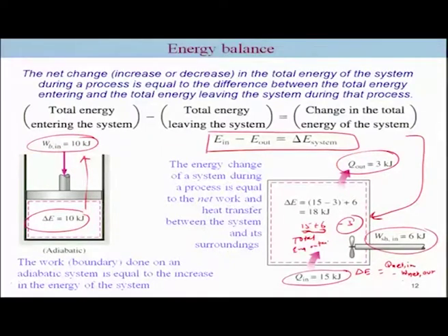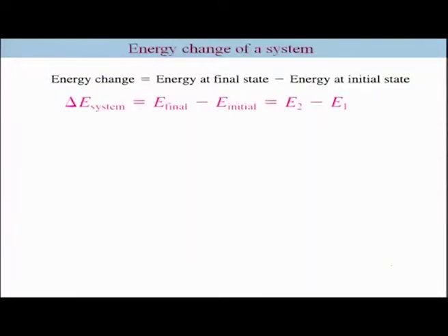Okay. So, what is the Q net in? It is nothing but 15 minus 3. What is the W net out? It is minus 6, and the minus of minus 6 is nothing but plus 6. Thus you can use this sign convention as well as the basic definition without considering the sign, just looking at known interaction directions. So, let me just further continue.